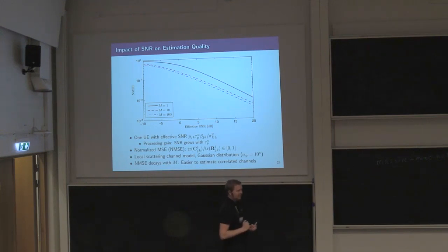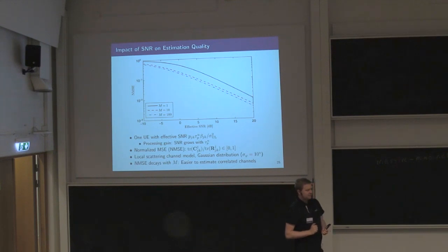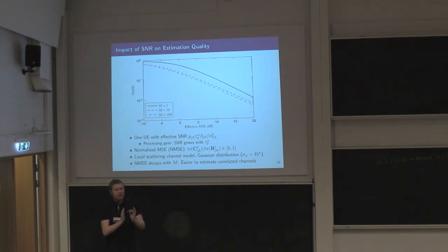Will the angular or standard deviation increase? When that increases, will it become easier or harder? So if you increase the standard deviation, you are increasing the spread from where the signals are coming in. And so higher standard deviation means less spatial correlation. So as you increase this one, these curves will move up towards the black one, and eventually it will be very close to that one. And if you instead are decreasing this number, you get more correlation, you get fewer eigenvalues that are strong, and then these curves will move further down.